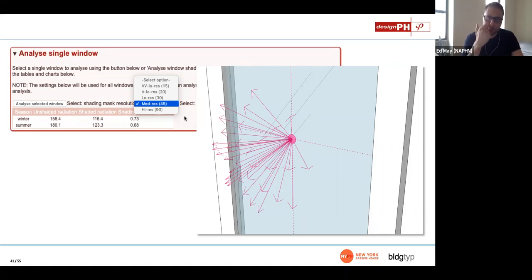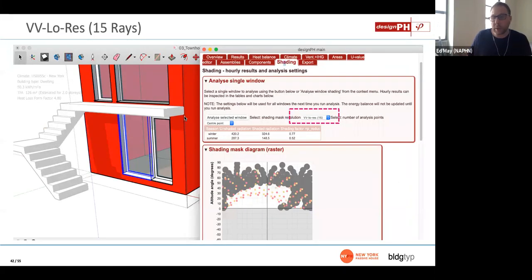So the usual recommendation here is, during most of your time working, to keep it set on the low resolution. Get everything set up and working at low resolution. Then when it comes time to export out to PHPP to do the assessment, you would bump it up to the higher resolution. As with everything else, we work with it in a slightly crude fashion, and then we bump it up to higher levels of detail when we're ready to export. So that's one level of controllability that we have. You can see the effect of it in the preview here.